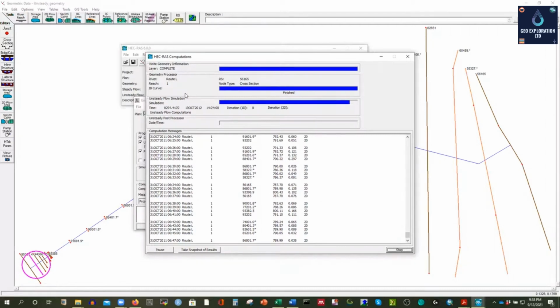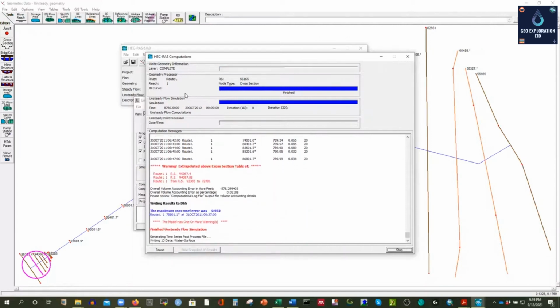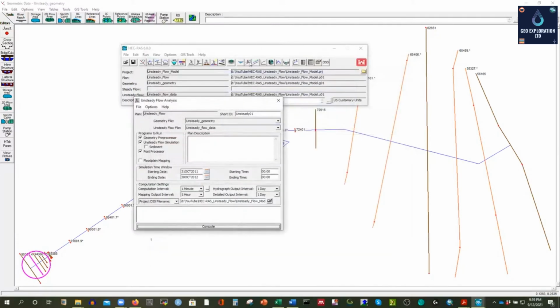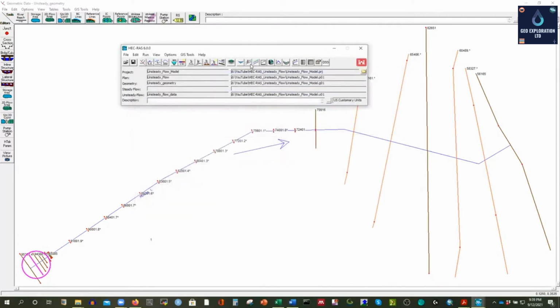And if our solver is stable, if the model is stable with the appropriate boundary conditions, the flow data that we have provided at the very upstream and the normal depth at the very downstream, because it is going to match the downstream boundary condition, it is going to create that one, 0.00023 from that upstream boundary condition. And in order to match that, see, this time it's multiplied 5 times. That's reasonable.